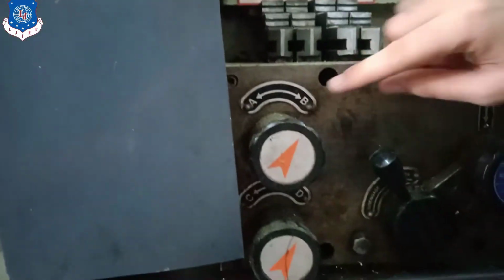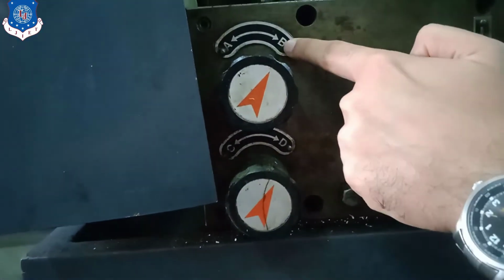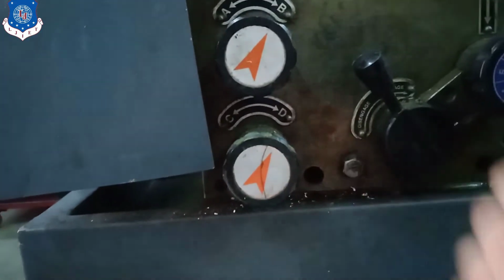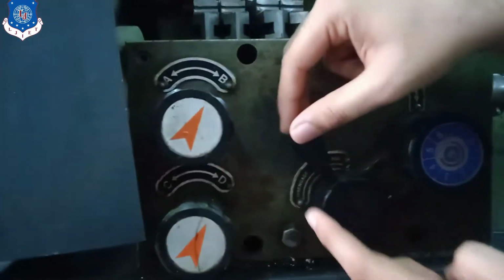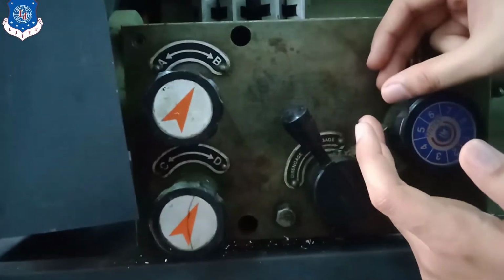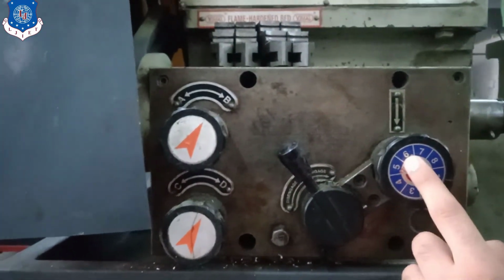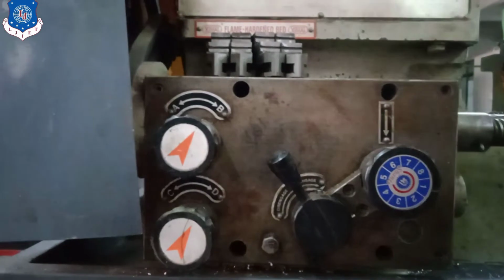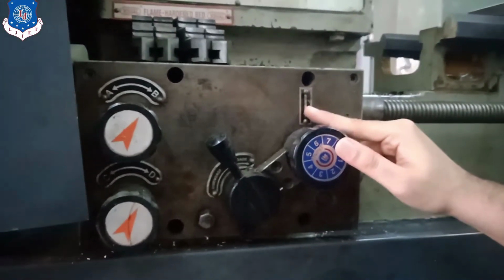So here also the combination of B and D lever is to be done. You can see the arrow is over the B lever and this arrow is towards the D lever. This lever is about the engage and disengage. Whenever the lever is in engage position, it will automatically go forward. Over here you can see lever number 6 is to be kept, because over here the 6 lever has been taken. So over here we will be placing this lever at the 6th position.